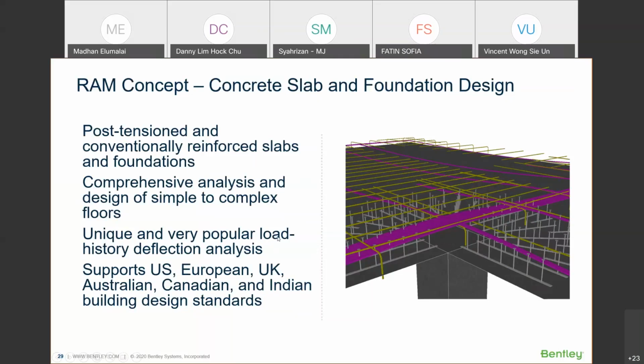We recently changed the name to long-term deflection analysis. It's available for all the international codes, and for Eurocodes, the national annex parameters are opened up for the user to fine-tune it as per your local national annex. RCDC, which I'll be explaining later, also has slab design, but that is not a finite element based slab design software. It can handle only one-way floors and two-way floors. It cannot handle flat slabs, whereas RAM Concept is meant for flat slabs. And slabs with openings also can be handled here, whereas in RCDC, slabs with openings is not recommended.